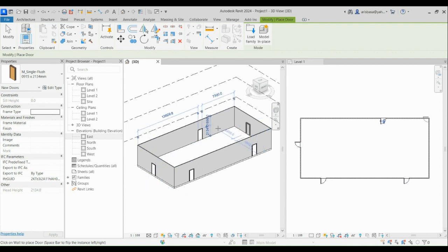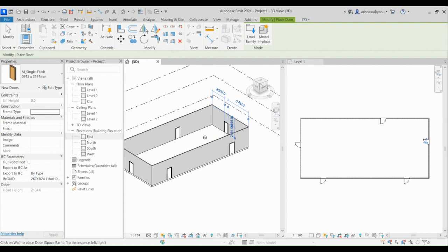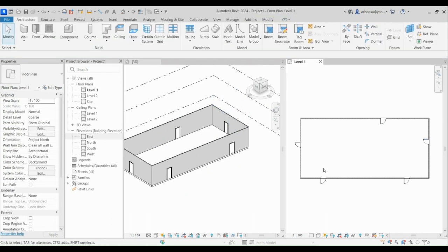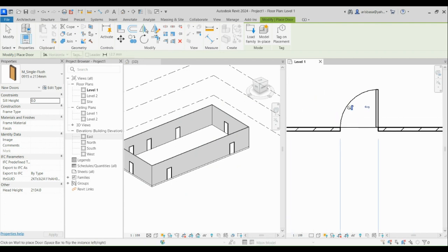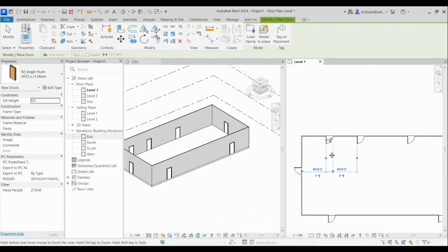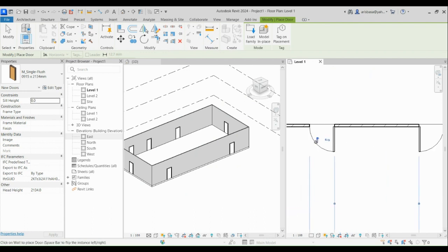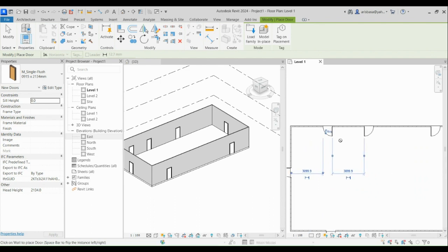You can directly put it on 3D. You can also place it on the plan view. And of course, I taught you last week, this is a control of where you want your door to be. If you want it to be swinging in the other direction, you just click these arrows.